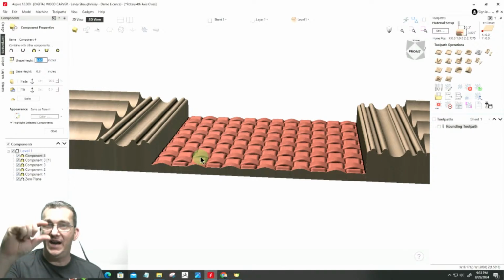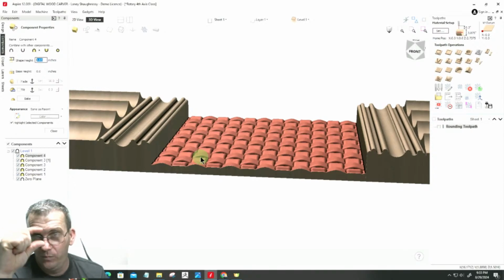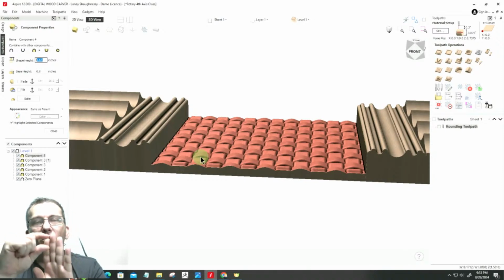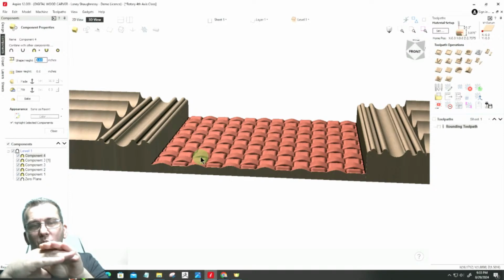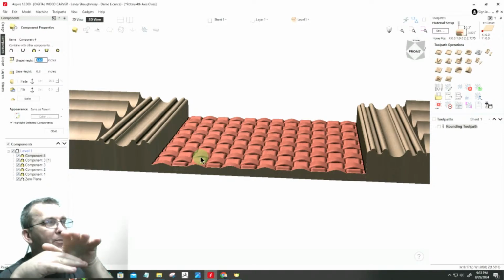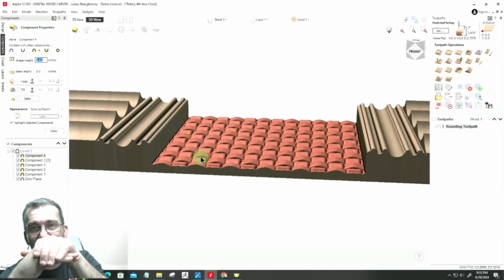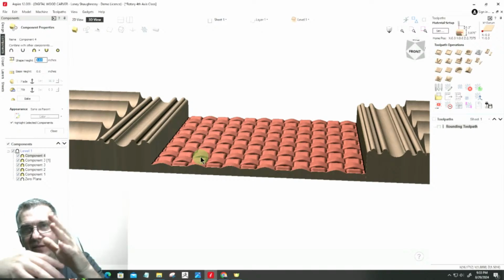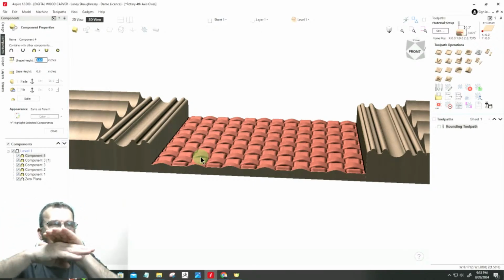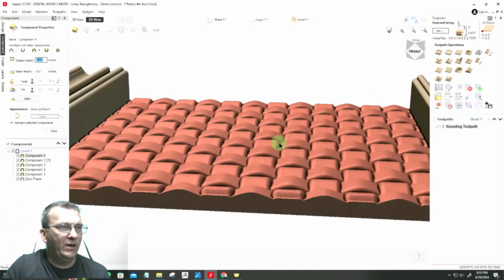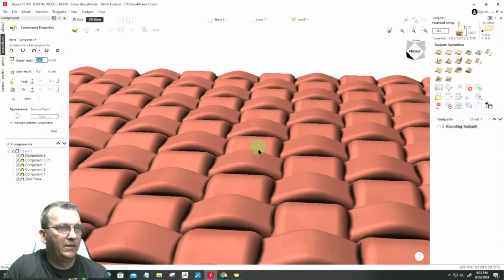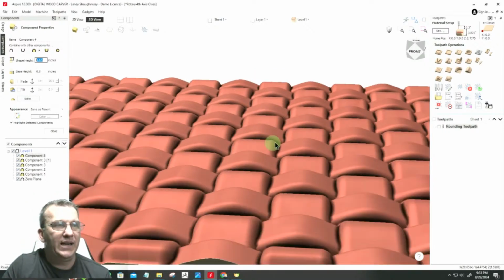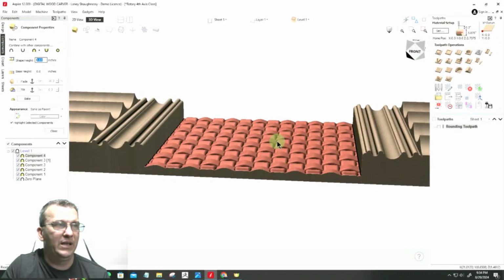So basically, my 1/2 inch tall weave band, when it wrapped over the other weave by that 30%, it added that 0.15 inches of height to that part, right? So the overall height is 0.65 instead of 0.5, because of that hump on that wrap. And that's fine.